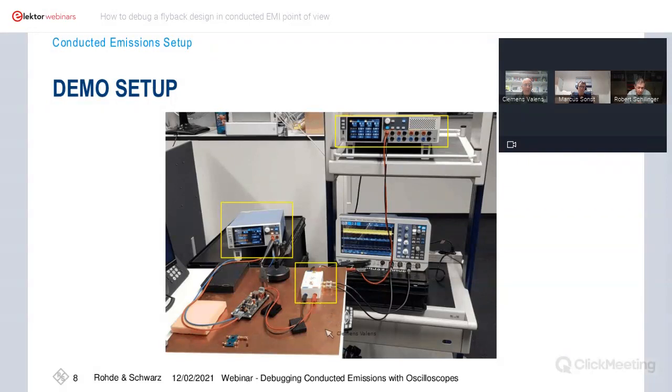On the back side of the LISN, between plus and minus, there is the earth connection, and the case is a metal case, and the measurement PCB inside the LISN is connected to the metal piece. If you put the metal piece on the copper plane, then you have also a connection. You can do it by a cable, or put the LISN on the conductive plane. I think these are the most important things to have good solutions for measuring differential and common mode, especially the common mode.